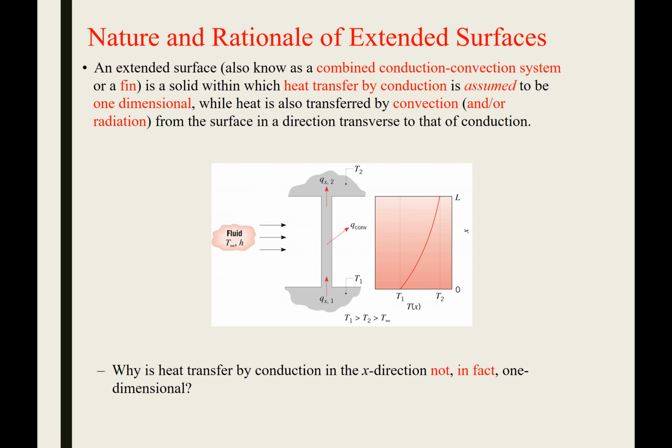Okay, so now we're going to get into something called extended surfaces. Often you want to increase the surface area. If you remember Newton's law of cooling, hA times delta T, if you have a bigger area, you'll be able to transfer more heat. So often you'll design a system that has extra surface area, designed to help improve heat transfer.